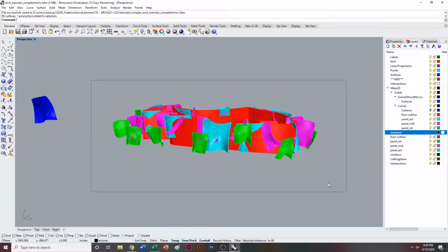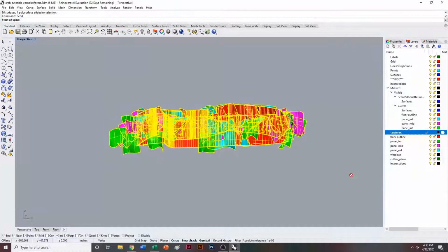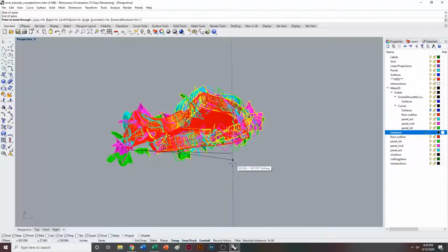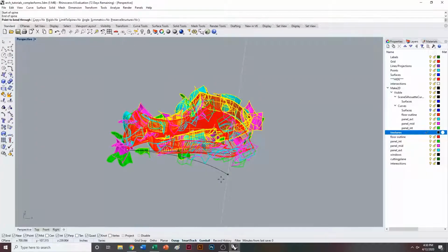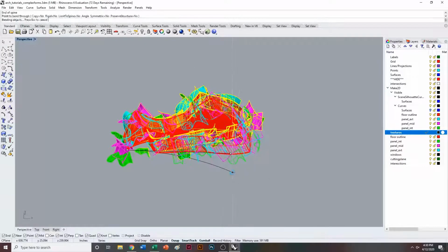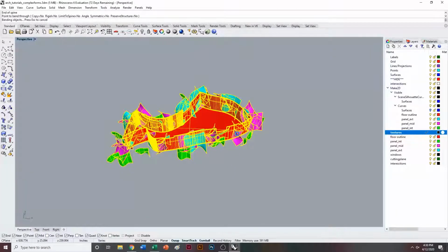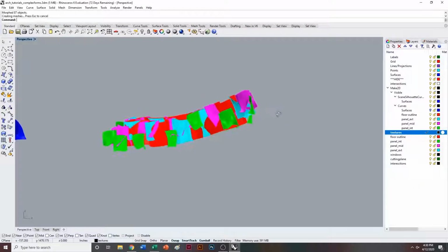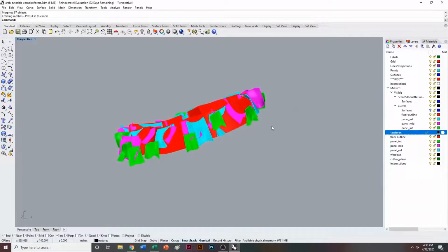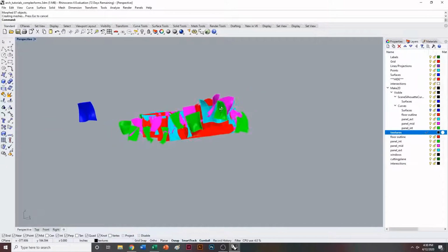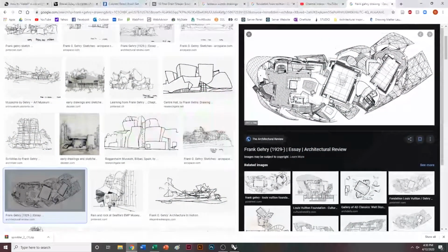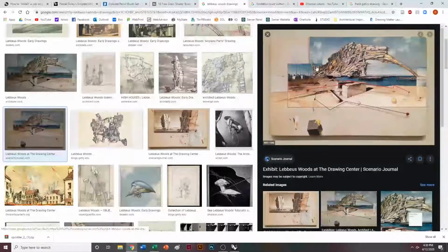And we're going to do what's called a bend command. So if we do bend, basically if you click at 2 points and start to click and drag, you'll notice that after it is done processing, the shape we just made actually gets bent to conform to that axis that we just did. So whereas before it was a straight line, now it's starting to bend back upwards. And I think Anakin, especially in your case, with something like this, kind of getting these arcs, that command is going to be very important.